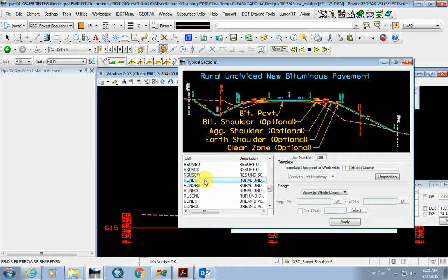You're always trying to meet letting dates, and I never did anything for the sake of automation purposes. I did whatever it takes to get the job done that was most efficient, and for me it was usually to automate the cross sections one time. And then I would go in, and with active chain control, that's really powerful, I could tie into any existing situation and knock out a job really quick.